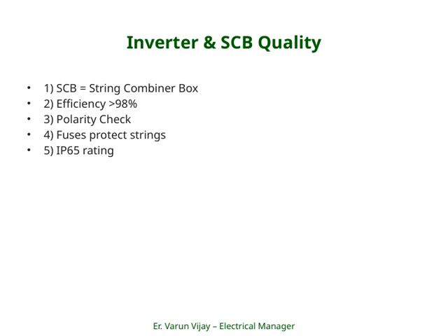Fuses are incorporated to protect the strings. Think of them as safety valves that safeguard against overcurrent or short circuits. Additionally, the IP65 rating indicates that these components are highly resistant to dust and water ingress, making them suitable for outdoor environments. All these features together highlight our commitment to high-quality, reliable solar power systems.